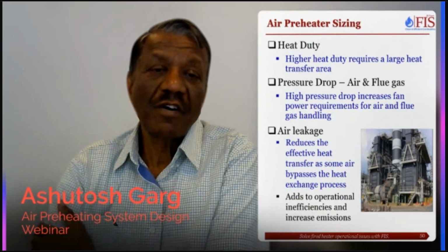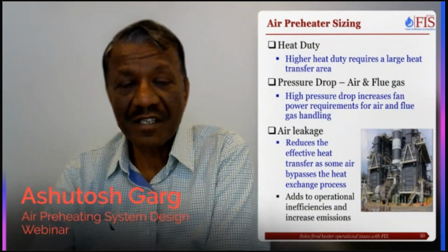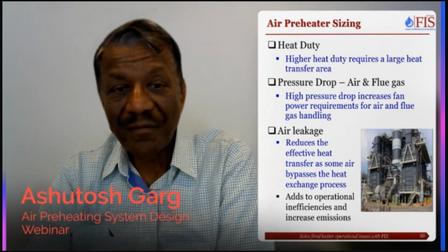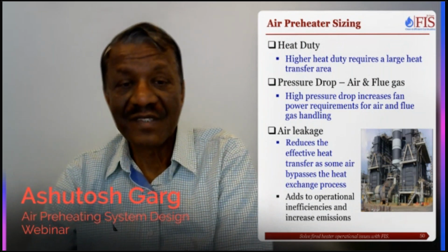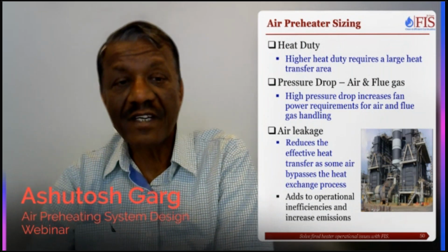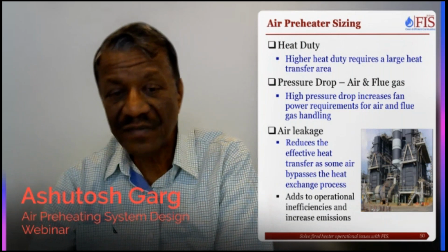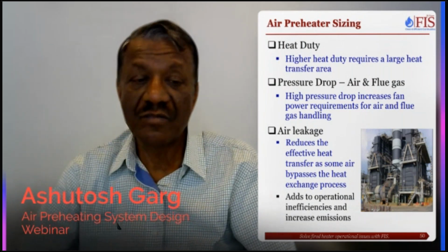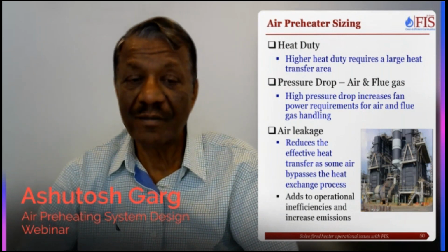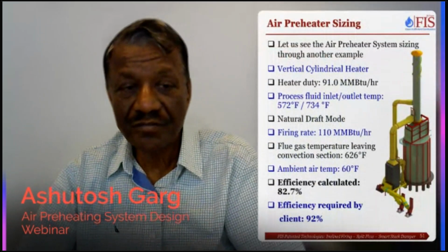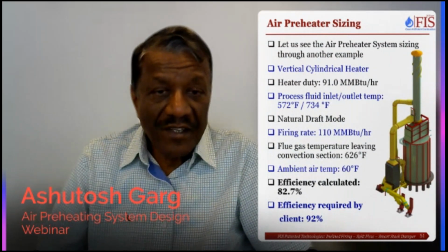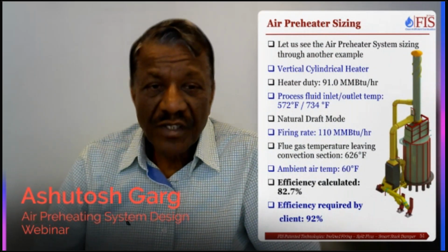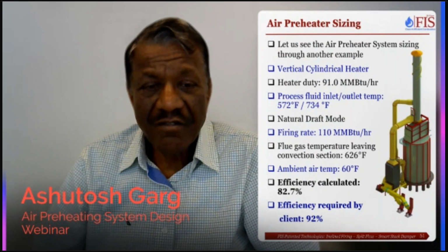So when you talk about air preheater sizing, there are several factors. Heat duty, that is one factor. Then the pressure drop on the air and flue gas side. And the third thing is air leakage, depending on whether you have a static or a rotary air preheater. So I have an example over here to show you. This is an actual case study, I believe.